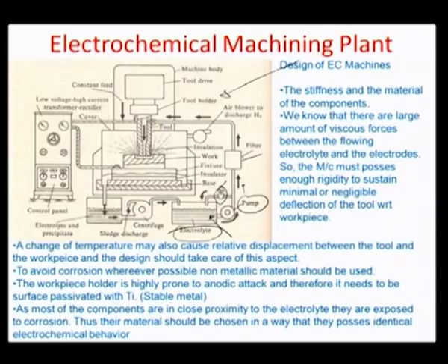So the electrolyte goes through a filter, this right here is the filter, and it is injected into the tool. This is a coaxial tool where you can see the electrolyte coming out of the tool in a very small slot at the end of the tool, right here, and then the electrolyte flows in both directions, okay, over the workpiece surface.